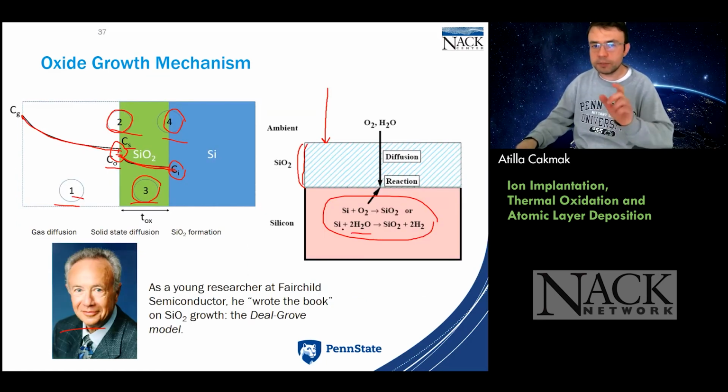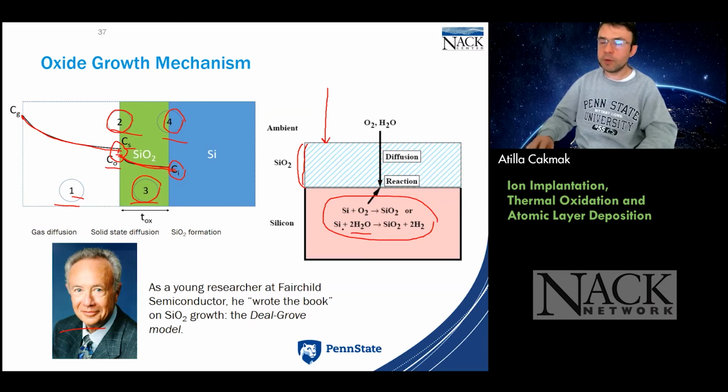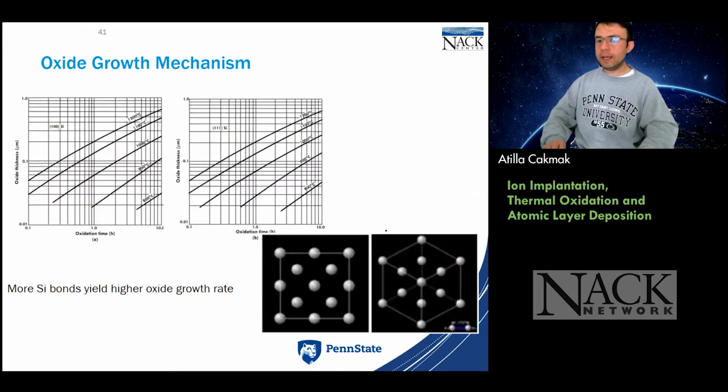Okay, coming back to the two different types of oxidation, wet oxidation and dry oxidation. Wet oxidation always gives us a much quicker result. So when we apply H2O, they're generally done for quicker but still dirty mechanisms to grow oxide. Why? H2O at the surface is absorbed much more efficiently. So the absorption coefficient is much higher for H2O introduction. So that's going to grow much quicker for that reason. But the end result is that the quality of the oxide, as we will see, is not great.